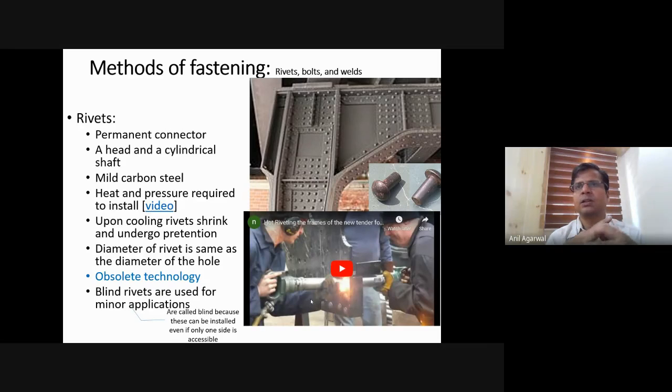Right. Washer is especially required when your bolt hole is slightly too large in comparison to the bolt, and you are afraid that the force transfer will not be very adequate, or there is a chance that the nut or the bolt head will not be able to get large enough bearing areas. I will explain to you what bolt head is. Please remind me to talk about the use of washers there when you see the geometry of a bolt.